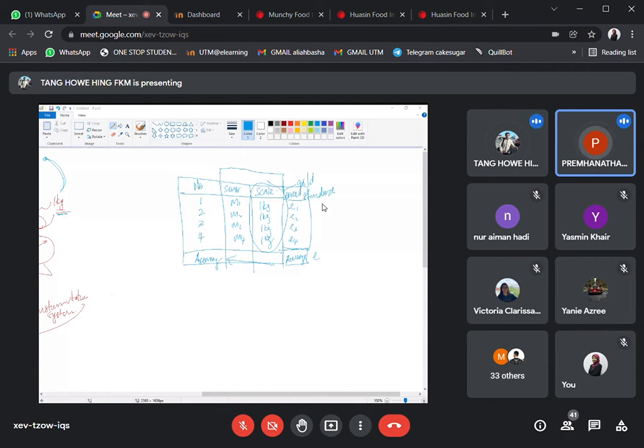So Doctor, just to clarify myself, we will get a voltage from the sensor, then we will plot it into the graph, which will give us the value of M. We will do this repeatedly for a constant weight. Then we can calculate the error using the formula that we already learned. Error is essentially just the comparison between the sensor and a gold standard.